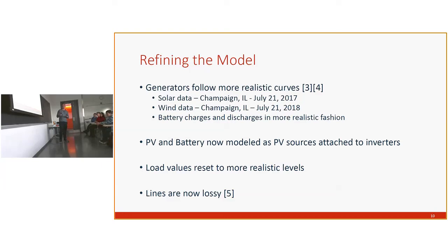The load values, they were artificially inflated before. They've been dropped down to more realistic levels, and the lines are now lossy. They're now being modeled taking the per unit length resistance, inductance, and capacitance from the IEEE 34 bus feeder.